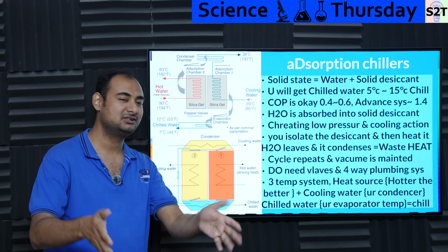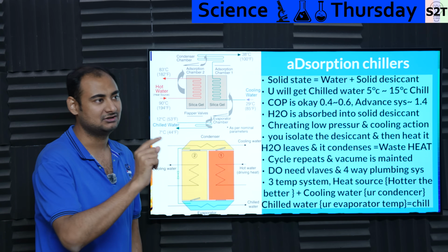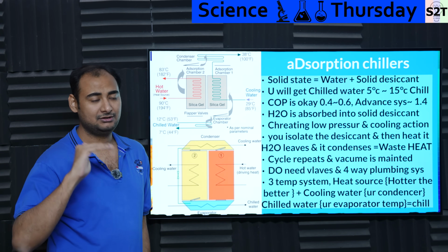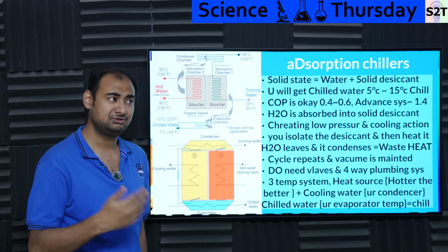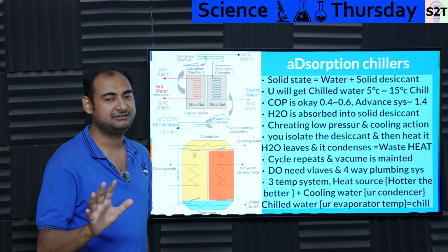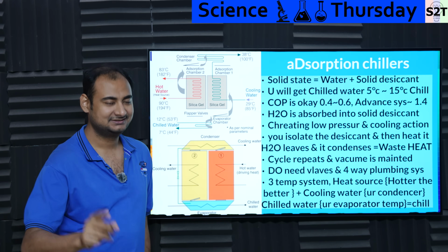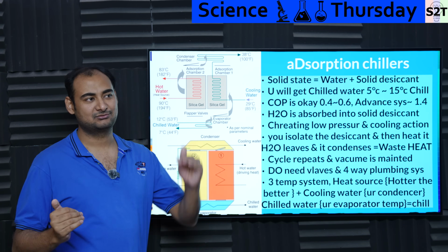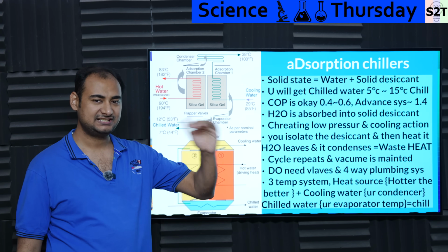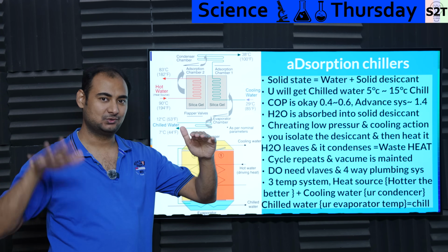What is the condenser? Basically cooling water temperature. They talk about the hot source temperature. That has gone down. When this sort of technology started, we would be lucky if we could get anything below 90. Now you can buy things the company will certify for 50 degrees Celsius. But the cooling water has to be cold, like 30 degrees Celsius. In India, I need something that works at like 70 degrees Celsius, while the cold water is only 45.